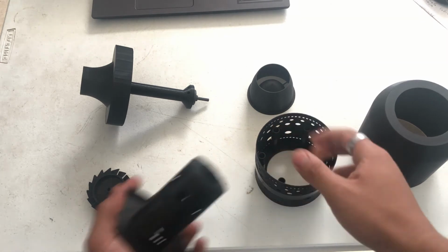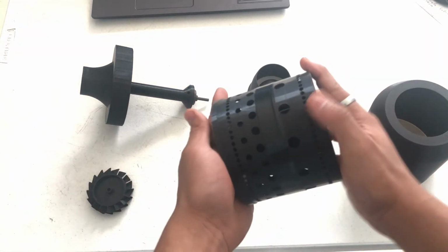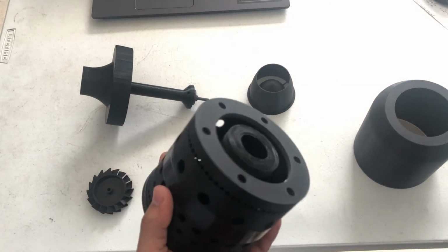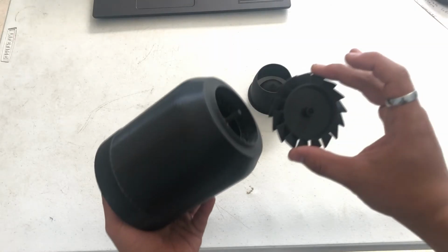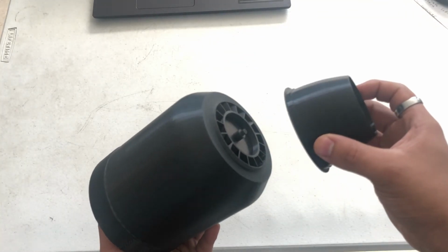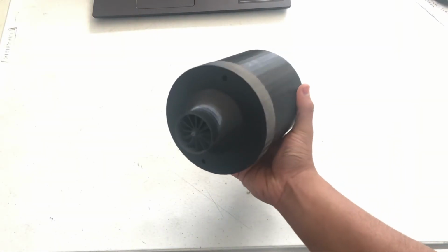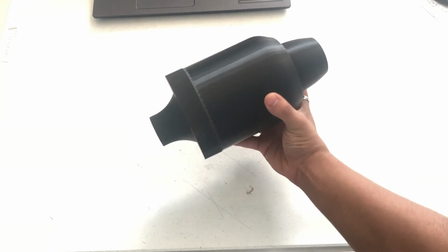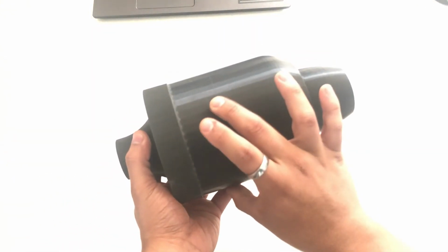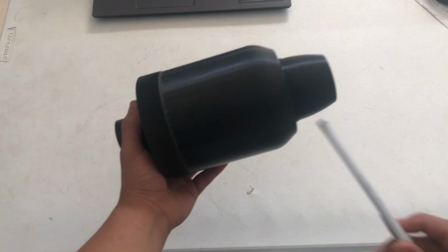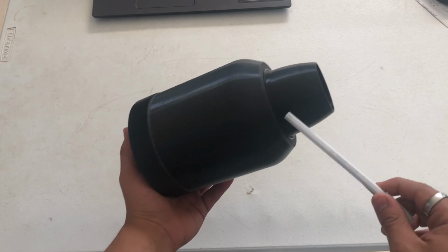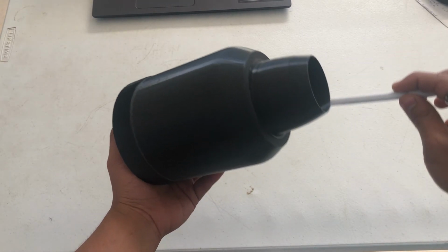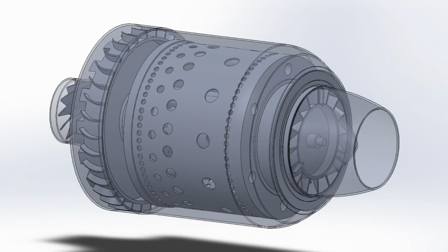Join it here and here, and it's ready. Now, put the turbine inserter right there. Once done, put the engine housing in place. Now, the turbine inserter, and finally, the exhaust nozzle. That's how it will look. We have the inlet, the combustion chamber area, and the outlet. Remember that this is a 3D printed model. It is not functional. However, the real ones can have clamps for better stiffness. This is how the microjet engine looks when it's working.